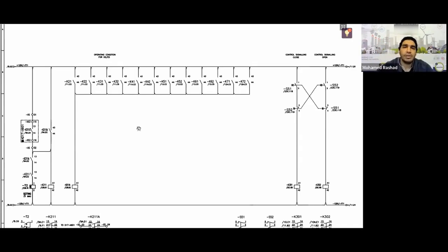Yes, so depending on the manufacturers, a disconnector takes, for example, 2 seconds, or 2.5 seconds, to say 3 seconds, 4 seconds. I haven't seen 5 seconds, but I'm telling you, like 5 seconds. It's simple. What will I do when I give a close command to any knife switch, any disconnector, any air switch? As soon as I give the close command, I will do the same action I used to do while supervising the charging time of the breaker's spring.